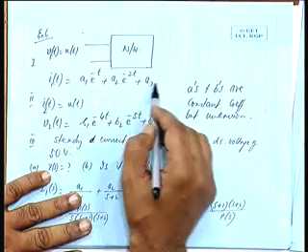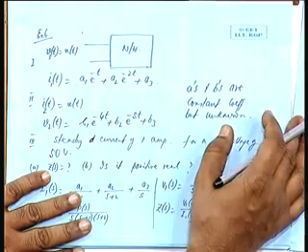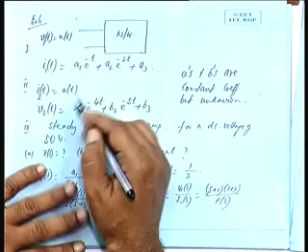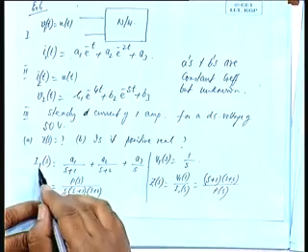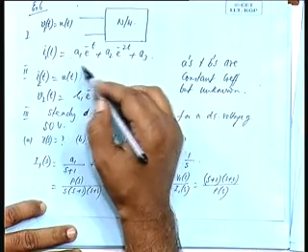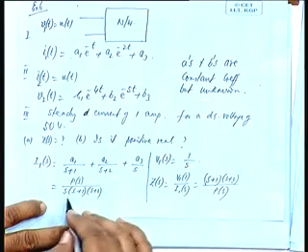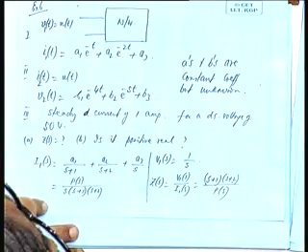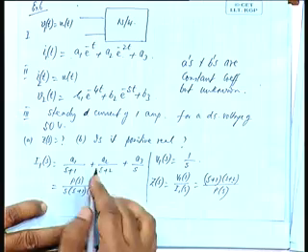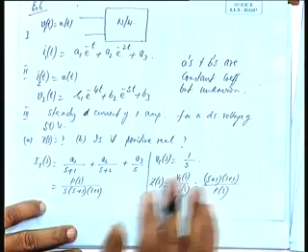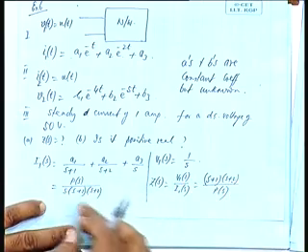Current is in this form, these A1, A2, A3 are not known. So, what could be the current transform? I1(S), A1 by S plus 1, A2 by S plus 2 plus A3 by S. So, that will be a common denominator, S into S plus 1, S plus 2. Numerator after all these additions, let it be P(S). So, I have identified this.